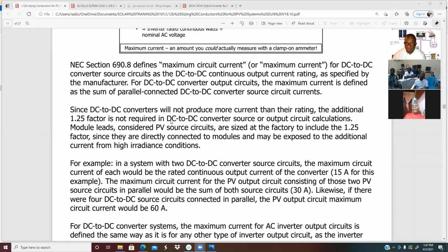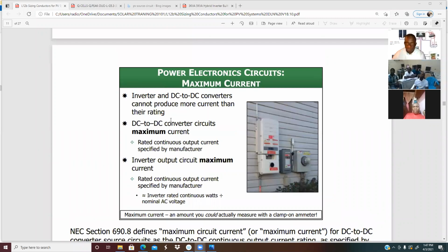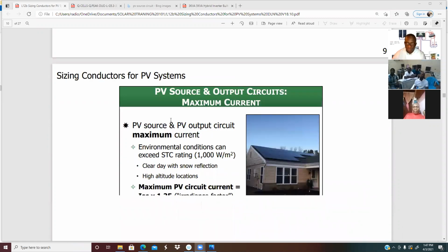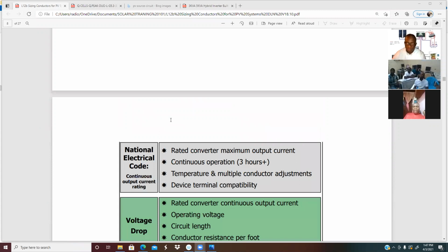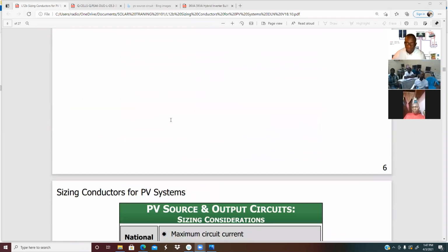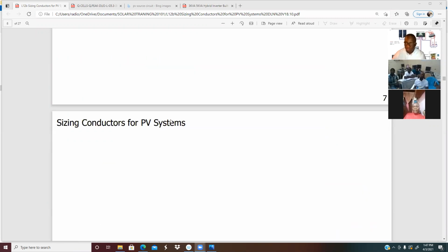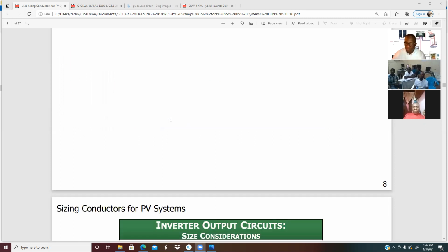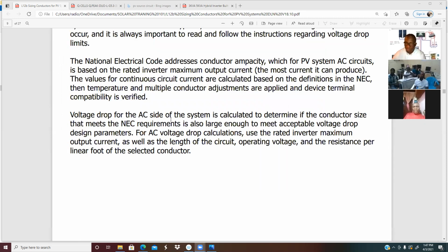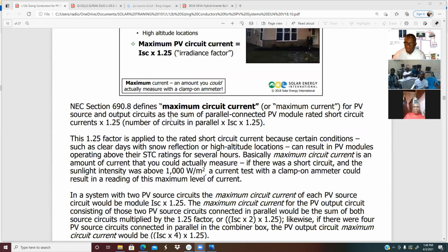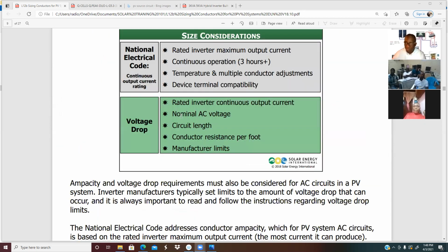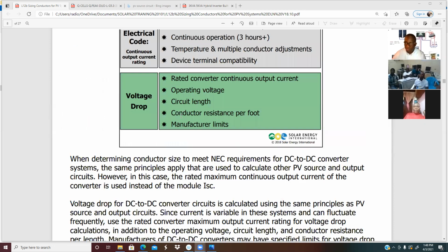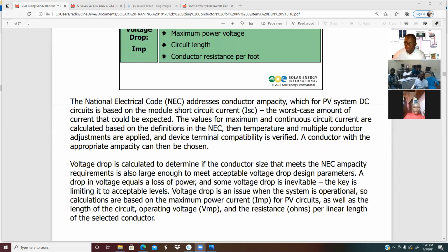And in this situation, when you are doing a DC system, you have to be very careful because DC doesn't take a slack connection. When you are doing these things, be very careful how you tighten your conductors, because where you connect a group of wires to make it one, you have to be very careful.